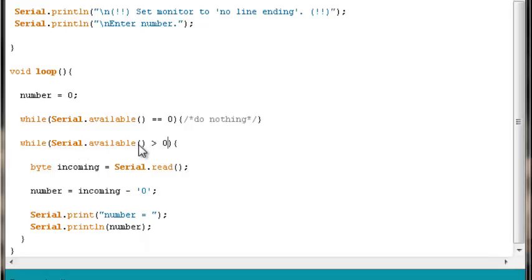Namely, whenever that Serial.available return value is something besides 0, which remember, if it's 0, it means there's nothing in the Arduino serial receive buffer. There are no bytes of data in there. Well, whenever there is a byte of data in there, the return value will be greater than 0. And then at that point, this test will be true, which will kick the while loop off and start the rest of the program. When this was out of here, we were just saying, well, whenever this is true, go ahead. So it's a matter of preference, but I tend to like to be as explicit as possible in the code, if it's possible to be.